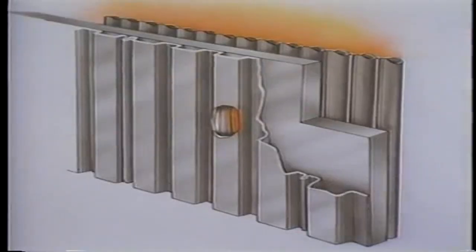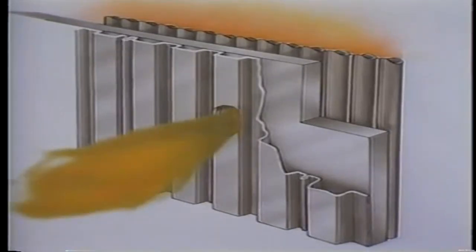Pressurized furnace boilers, on the other hand, present an operator with a different problem. Pressurized furnace boilers operate under a slight positive pressure. This means that a leak in the boiler casing may allow flame or hot gas to get out of the boiler. Flames extending outside the boiler casing can cause fires and create a safety problem for plant personnel. In most cases, a leak in a pressurized furnace boiler requires an immediate shutdown.